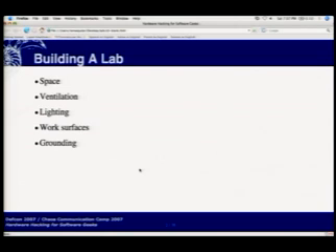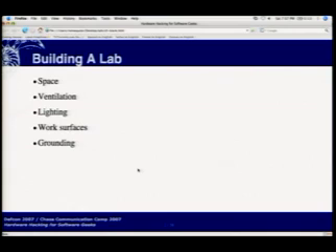The fumes from etching your own circuit boards are very unpleasant. You've got to keep your lungs in good shape, or you're not going to be doing this for very long. Lighting is also key. Basically, the brighter your lights are, the better your eyes' resolving power is. It's just a matter of having small pupils.